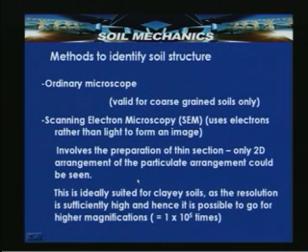So, having seen different particle arrangements, we said that single grained arrangement can be there for bulky particles. Honeycomb structure can be possible for silt particles predominantly, and clays, representing fine grained soils, can have flocculent structure or dispersed structure. It depends upon the environment in which the suspension is occurring. Then the question will come, how to identify the soil structure.